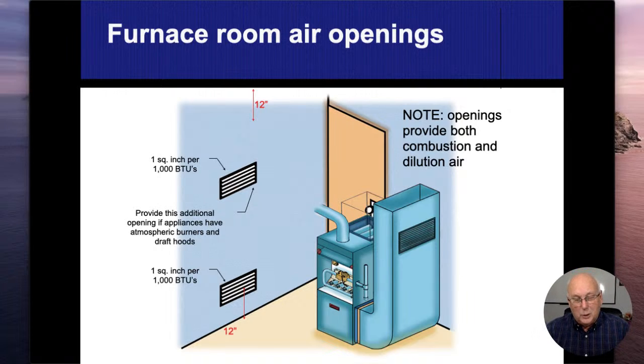Now, because these grills eat up those spaces, a 10 by 10 isn't going to be big enough. So typically we want to be about 25% more than what that is. I think I got another slide coming up a little bit that explains how much gets eaten up. I know with the wood grills, there's only 25% that comes through, where it's kind of the other way around with the metal grills. So we do need to be significantly bigger. All right, 1 high, 1 low.